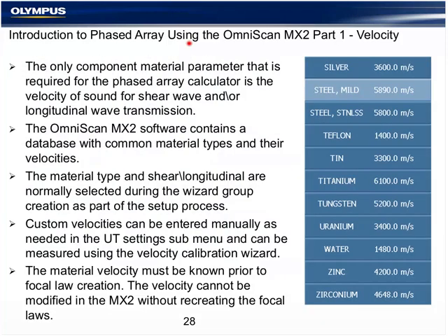So that was 2 of our 3 hardware parts: probe, wedge, material. When we talk about material, the third part, we're really talking about only velocity. The thickness of the material, the width, the weld bevel, all of those things can be modified after beam formation or after acquisition and reverse engineered in the data if necessary.